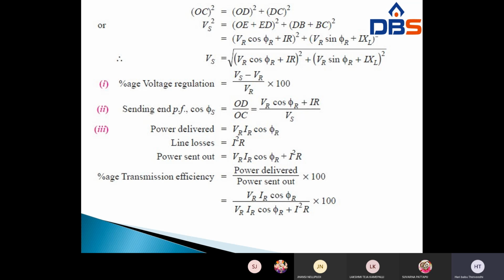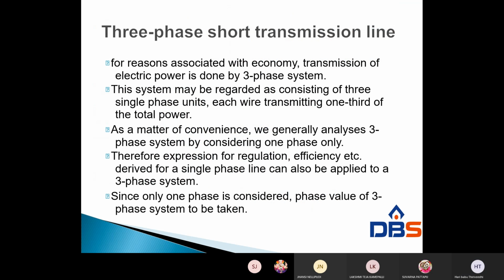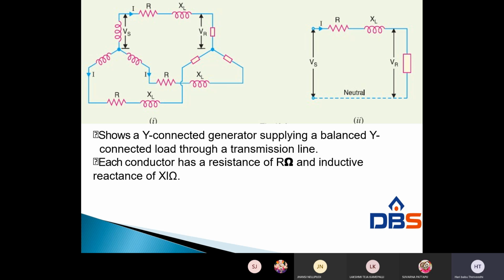And generally we have to calculate phase values only, single phase values only. After that we have to calculate three phase. If it is a three phase circuit, first calculate the phase values, and then those phase values must be converted into three phase values also. So look at the figure. This we also have to calculate.